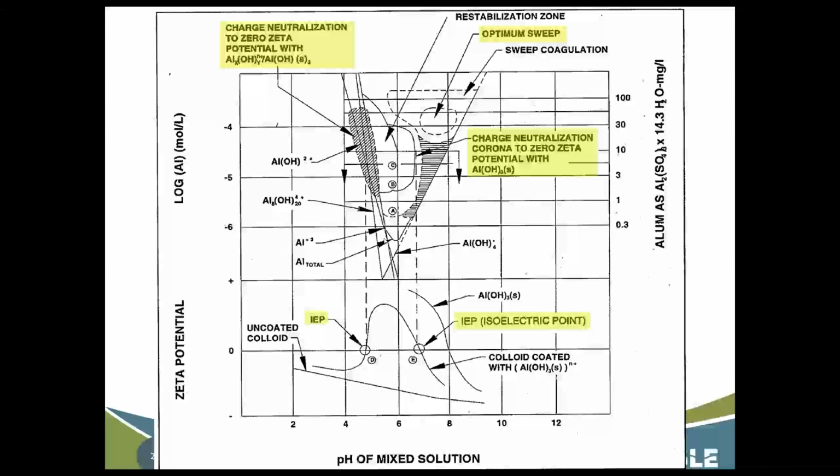These are the different types of oxides that you can form, and they behave differently. And also, we've got this general V outline here, and basically anywhere within this V is the acceptable pH range for alum. And as you can see, it's pretty narrow. Especially when you're trying to hit this little window right here, you're really looking at between like 6 and just over 8. This will be important when we look at the ferric version of this graph next.